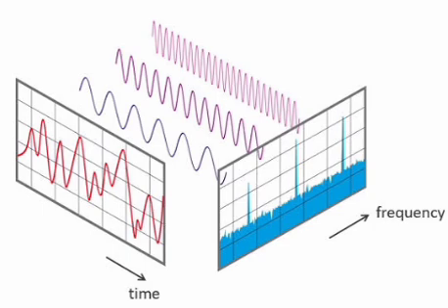ROC is R. Convolution: x1 of t convolved with x2 of t has Laplace transform X1 of s into X2 of s. ROC is R1 intersection R2. Remember, convolution means R1 intersection R2. Integration from minus infinity to t of x of tau d tau equals 1 by s X of s, with ROC R1 intersection real part of s greater than 0, where x1 of t has ROC R1 and x2 of t has ROC R2 respectively.